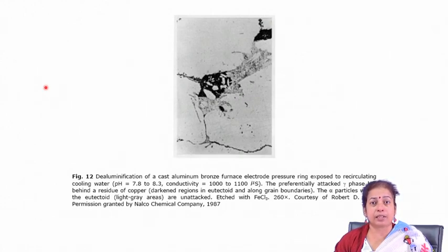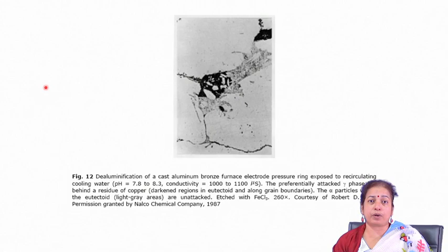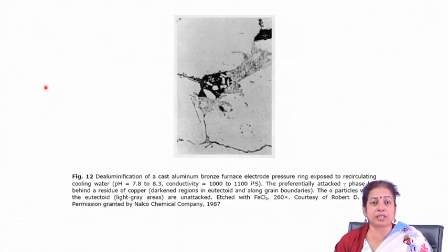So, you have to understand which element or compound, or what the composition of the grain boundaries is after the precipitation, and if it is enriched with different phases, you have to be careful in applying it in the environment. So, what you have to do? You have to homogenize the alloy prior to its application, or you can also get rid of this problem by typical cathodic protection, anodic protection, and also by painting.